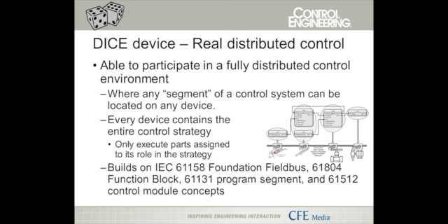Now, this is not rocket science. This has actually already been developed in some of these industrial standards that I've talked about, such as the 61158 Foundation Fieldbus discussions, 61804 Function Block Programming, 61131 Program Segments, 61512 Control Module Concepts. All of these talk about how you take a control problem and partition it to make it solvable, but that same partitioning allows you to put these into the smaller devices.